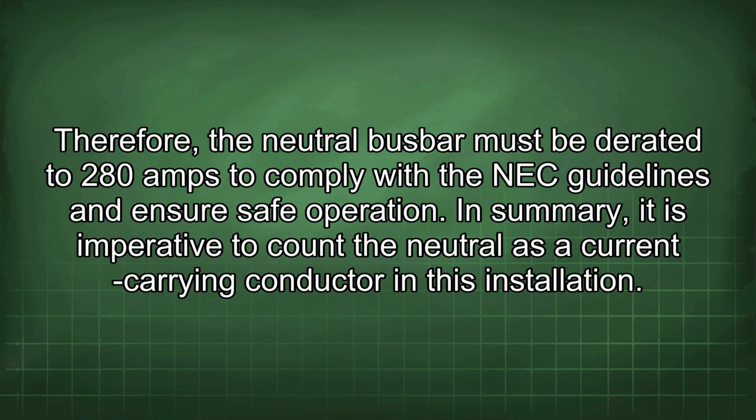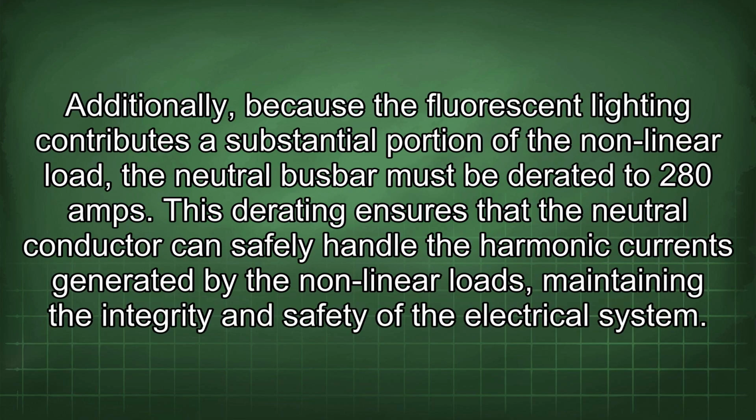In summary, it is imperative to count the neutral as a current carrying conductor in this installation. Additionally, because the fluorescent lighting contributes a substantial portion of the nonlinear load, the neutral busbar must be derated to 280 amps. This derating ensures that the neutral conductor can safely handle the harmonic currents generated by the nonlinear loads, maintaining the integrity and safety of the electrical system.